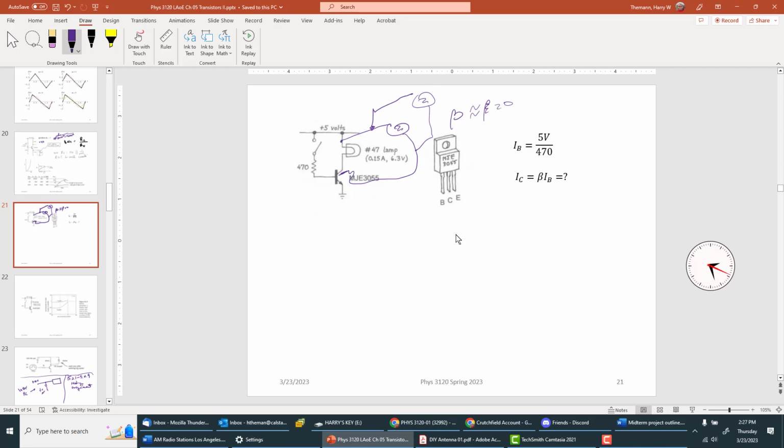Across the way, we got these two massive coils, and when I do this with that, it goes for like 2 or 3 seconds. It just keeps arcing across. And that can be dangerous. At the very least, what it does is it would wear switches out. And so back in the day, the original house switches were actually rotary, and inside, you'd crank it, a spring would wind up, and then it would rotate this thing, and these things were sticking down, and the thing would rotate into it. And they had to be massive